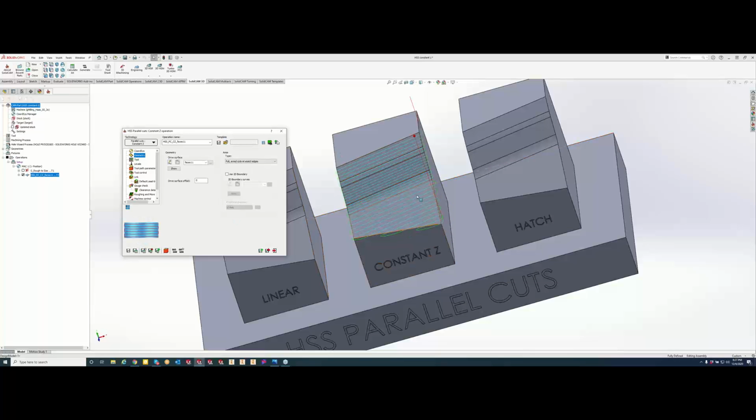Now, typically on a part like this, we don't have to worry about it, but coming in here, what does a gouge check do? Basically, by enabling this, and I'm going to turn off our check surfaces here, I'm telling it not to gouge the drive surface, to check the gouge against my tool shaft as well as my tool tip. And if you're worried about your arbor or your holder, you can turn that on as well.